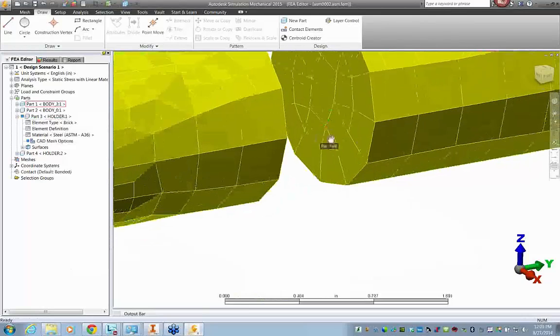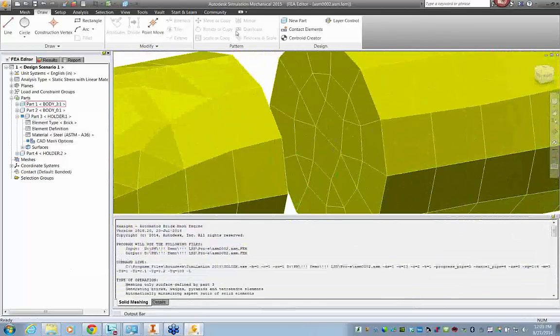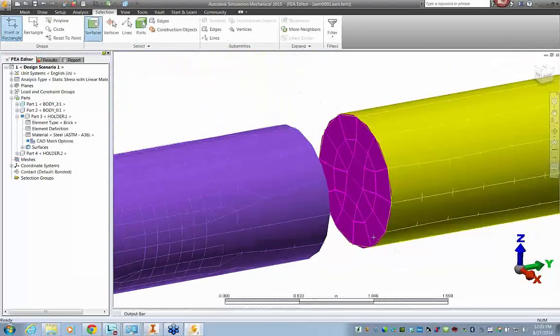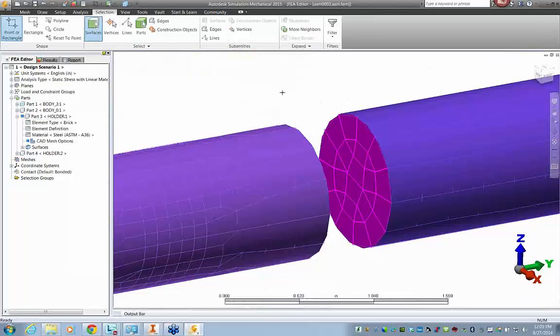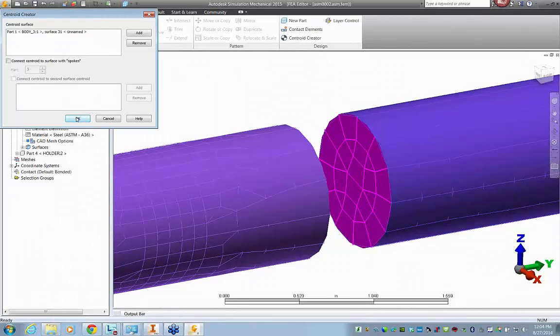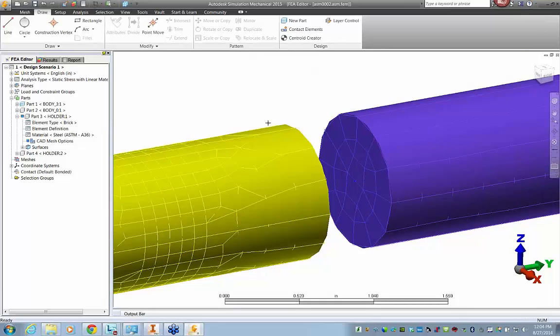And we're looking at this surface. Let's actually select the surface. This surface right here. And let's say I want to find out where the center of that surface is. And it's pretty common to be able to maybe add rotations or fix the center point. People often need to be able to find the center point for objects. So after selecting that surface, I believe I go to Draw, and then I create a centroid. So when I do that, all I do is hit OK, and it creates that centroid for me.